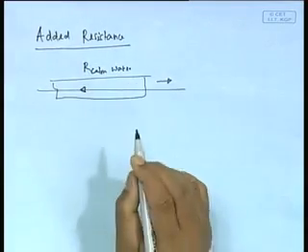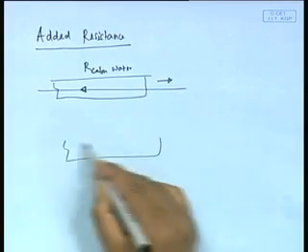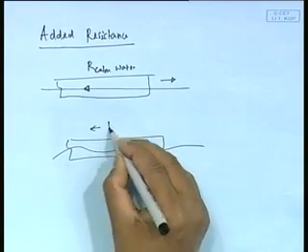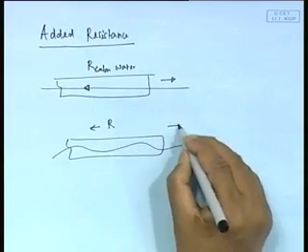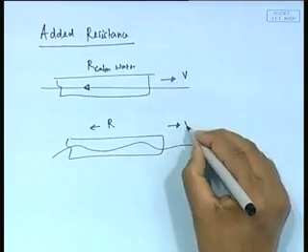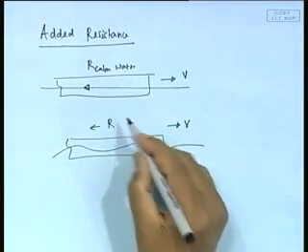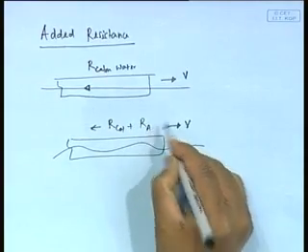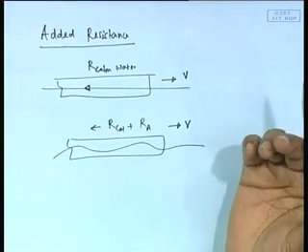But if you were to go in a wave, then I get an R. Now, this R happens to be more than the calm water R, that is, this becomes R calm plus R added. Basically it is more, and if you take this minus that, what you call is additional resistance.